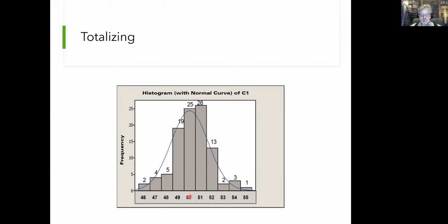So say 50 was your target, right? So your mean, the center of your counts, is at 50. But then you find that there were some you measured at 49, some were at 48, 47, 46, but they tailed off. None of them were so short that they were below 46. Good, especially if your limit was 45. And none of them were larger than 55. Great, so at the high end, nothing went higher than the highest limit.